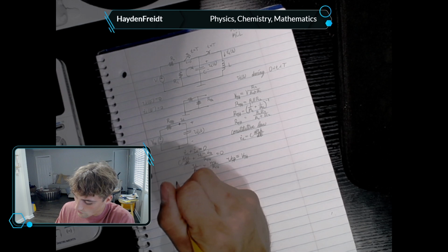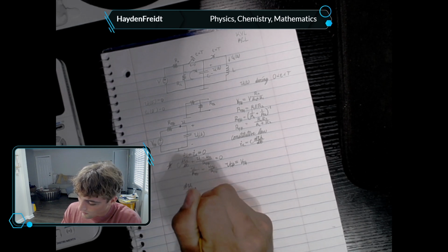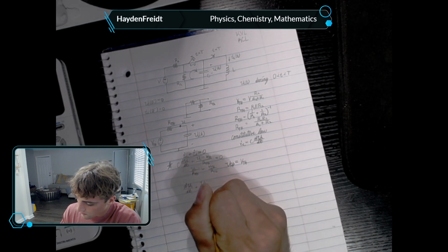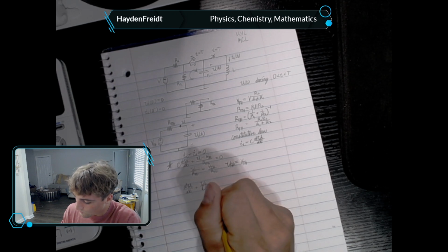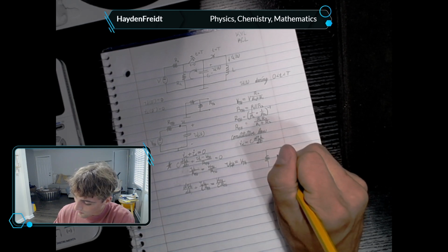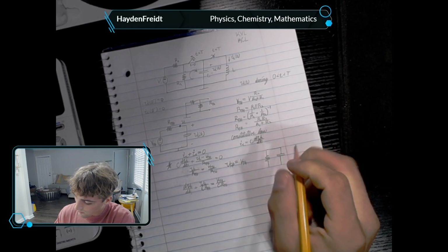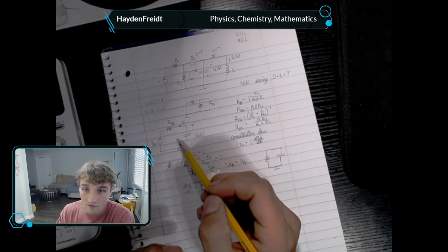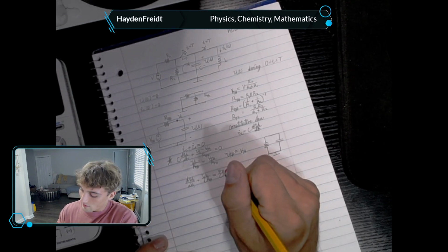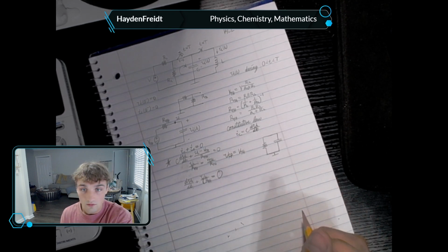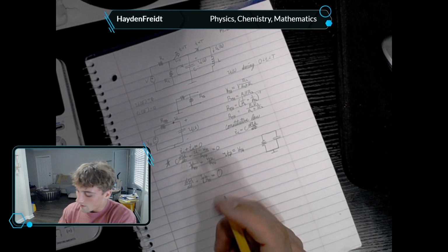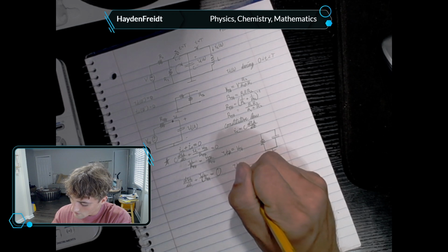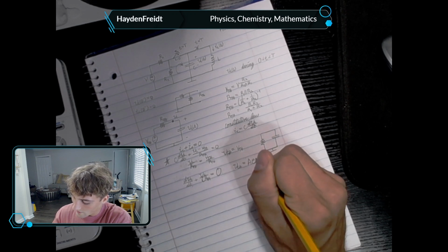Okay, now the homogeneous solution is a little different. It's dVC/dt plus VC over C times RTH, our capacitance times our Thevenin resistance, equals 0. And then we'll draw ground for reference. Okay, it's going to look like that. All right, we're not going to have our VTH here. We're not going to have the supply. We don't want to drive. So for our homogeneous solution, we're going to assume that VCH equals a form like this.